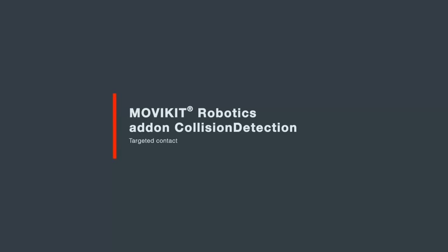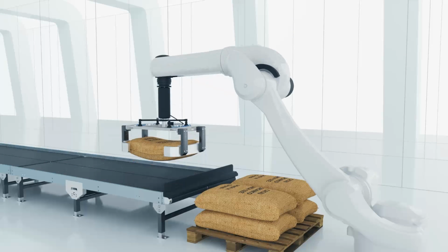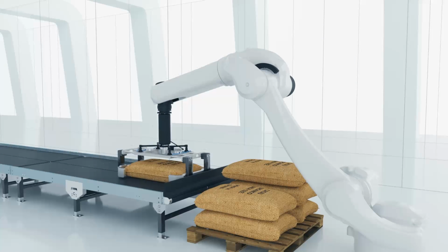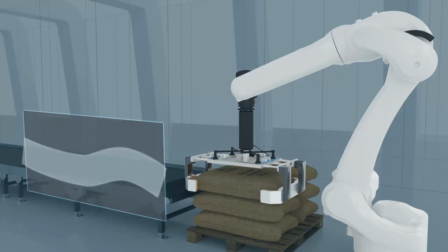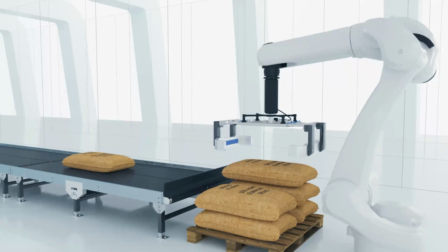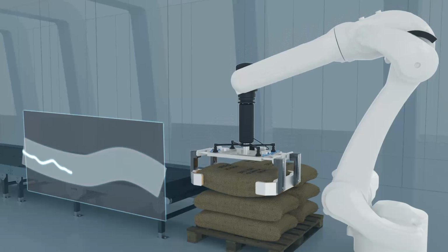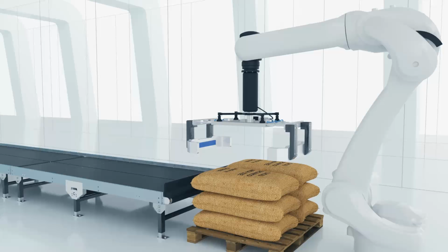In contrast to the undesired collisions which have been examined so far, we also support the application case of a desired collision. In this case, contact is intentionally made in order to determine the flexible effective stack height. The major advantage of this function is that no expensive force torque sensor is required on the picker arm. Instead, the contact is detected by measuring the motor currents and evaluation using the dynamic model.